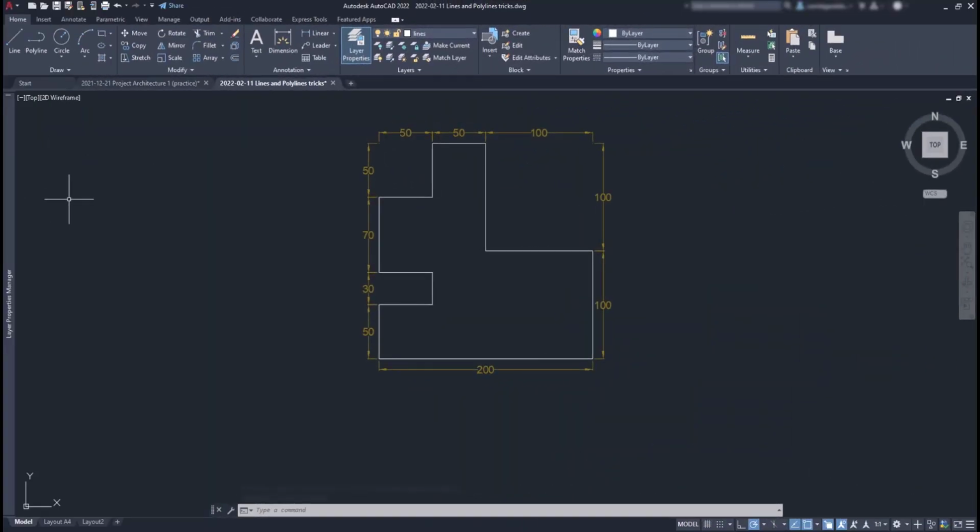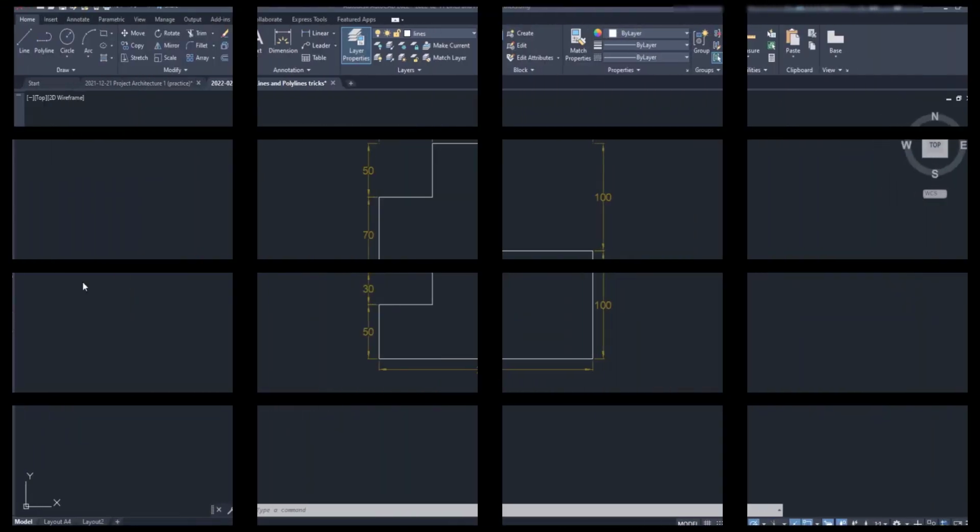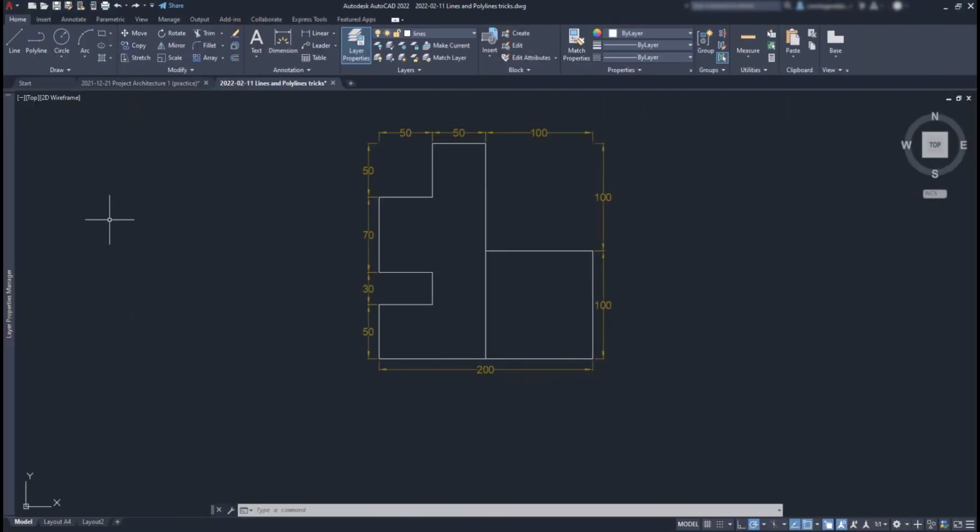So in conclusion, I think this command can be useful if we need to place equally spaced points along a certain direction. So in this case, I can draw a line, then use divide, and erase the line at the end. With the command measure, instead of specifying the number of points, I set the length between each of them. As an example, let's type 20, and I divided the line in 5 sections.